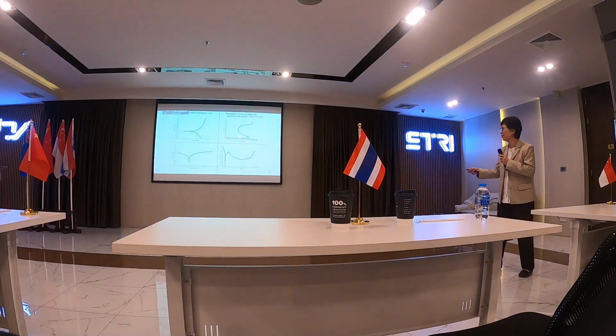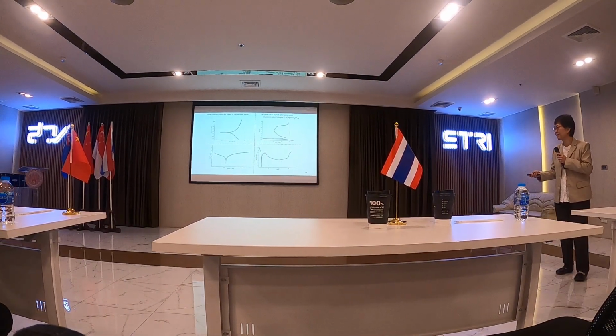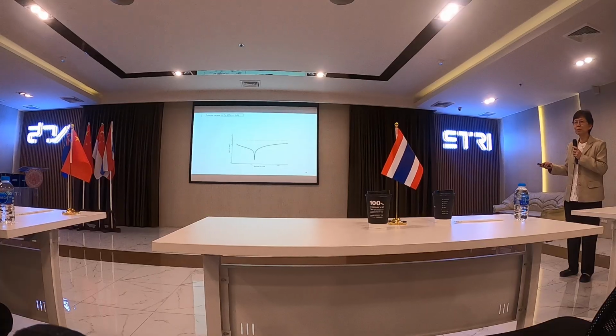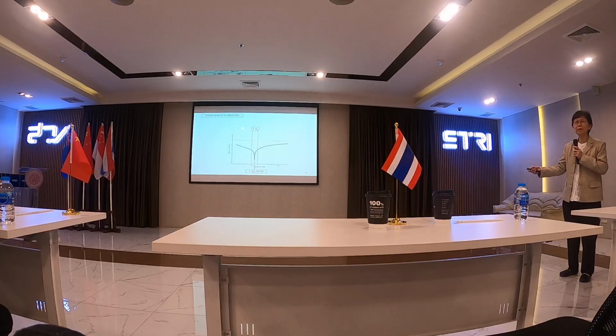You will find this type of curve, instead of this direction, you use this curve instead. Okay. So when you study the material, we select the suitable range of the potential to study. First of all, we have to know the corrosion potential, and then we can measure the corrosion polarization resistance of the material in the very narrow potential range. Then this narrow potential range doesn't affect the surface of the material.